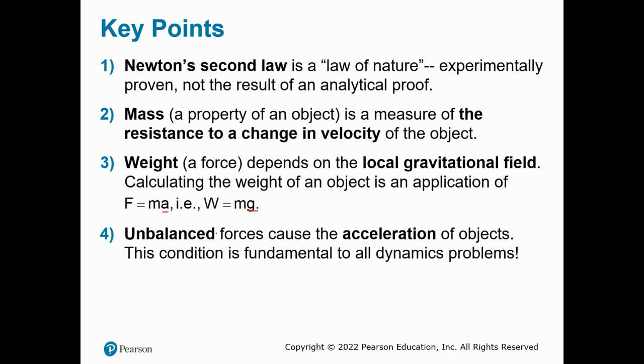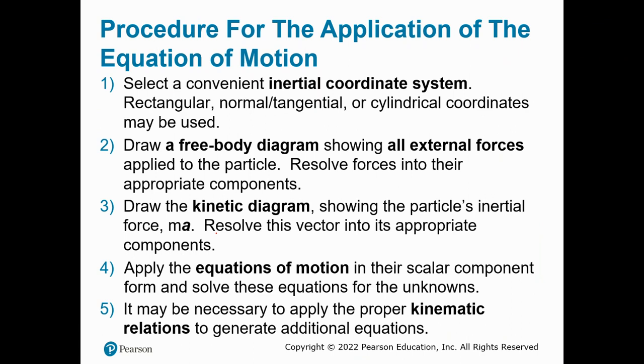Unbalanced forces cause the acceleration of objects. This condition is fundamental to all dynamic problems. So whenever you see problems, the procedure for application of the equations of motion is to select a convenient inertial coordinate system: rectangular, sometimes normal-tangential, or cylindrical coordinates, depending on the problem. We're going to draw free body diagrams. That free body diagram is going to show all the external forces applied to the particle, resolve forces into appropriate components, and then later we're going to show the kinetic diagram.